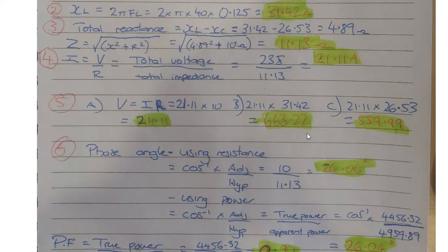In the previous video, the PowerPoint for this topic, one of the things it talked about was that we don't want to use unity power factor because of the possibility of unstable voltage or voltage spikes. And that's what we see here. Even though we've only got 235 volts on the input, you can see on that inductor, we're now at 663 volts. And that's 663 real volts, so that's going to present a hazard to our insulation, because high voltage breaks down insulation, and potentially to us, to people, right? 663 volts is a big number.